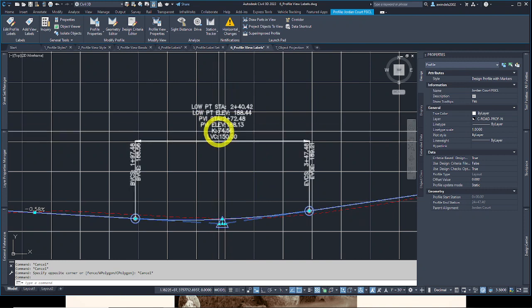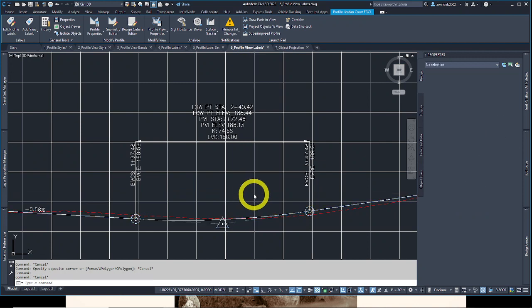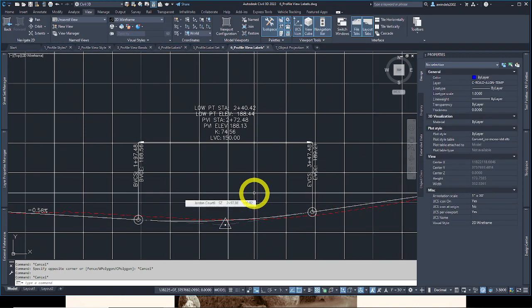The K value is the abruptness of the curve, or you could say the higher the K value factor or ratio, the more gentle and generally safer the vertical curve is in a highway for design, for things like headlight and sight distances. So the smaller the K value, conversely, expresses a more abrupt, more aggressive vertical curve, almost like a straight line shift, which is not easy to drive over, if you could imagine, with wheels.